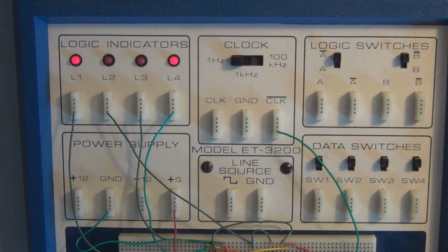So to summarize, we've introduced the idea of a clocked input to a Set-Clear flip-flop in addition to the control inputs, and the clock triggers the control input to change the Q output either on the leading edge or the falling edge of a clock signal.